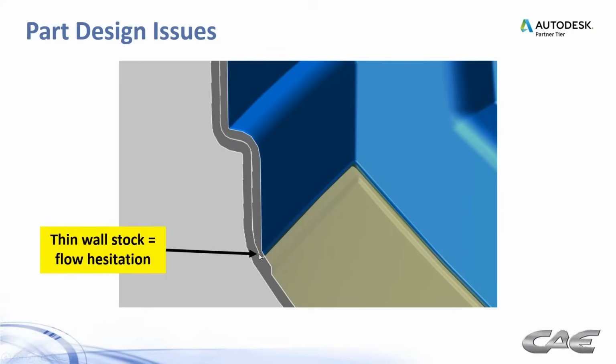And in this case, this was a part design issue. It's two things: this part design issue, but also the limited gate location. This thin area here is causing some hesitation in the flow front going around that window area.